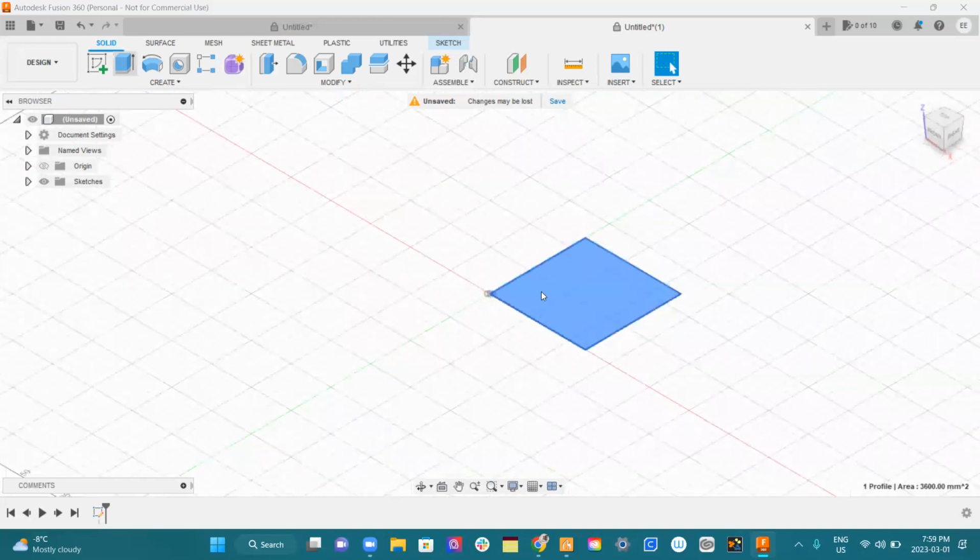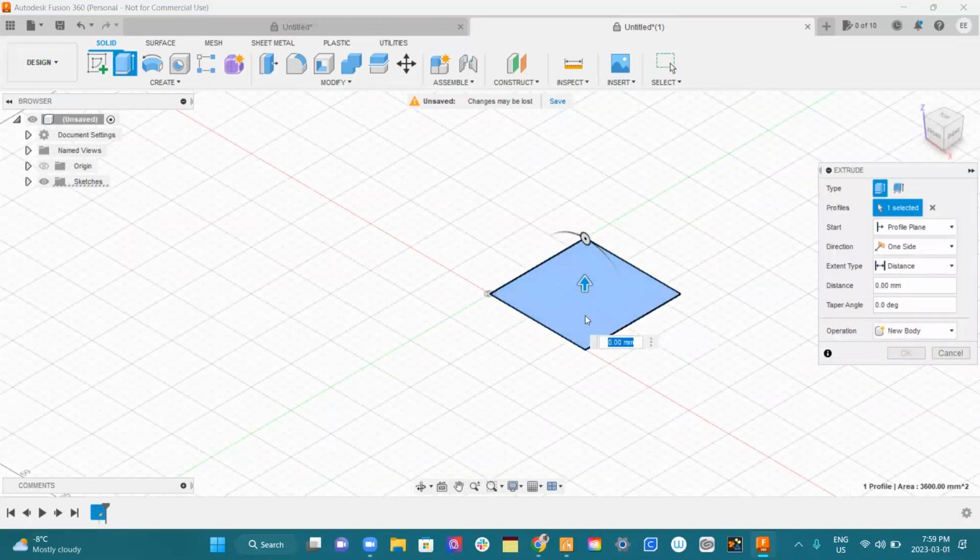So I click on extrude, and this is flat, and by default it's trying to say, okay, I've got something flat, and I'm going to bring it up and make a cube. The funny thing I'm going to do now is drive it down because I'm carving into it, and so I want flat to end up being the top of my material instead of the bottom of it, just because it makes references easier. So I can set a negative dimension, and then this will make a shape like this. I know that happens to be 19 millimeters. This is kind of funny. It sticks out the bottom. If you want to measure a depth, you do it like that, and measure that. There are two sides here. There's inside, and then there's outside.